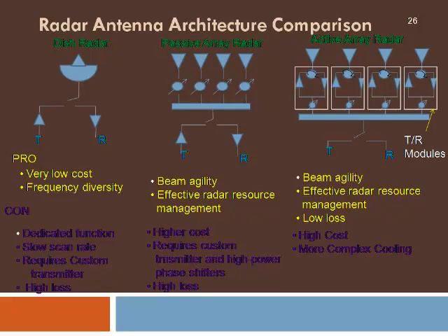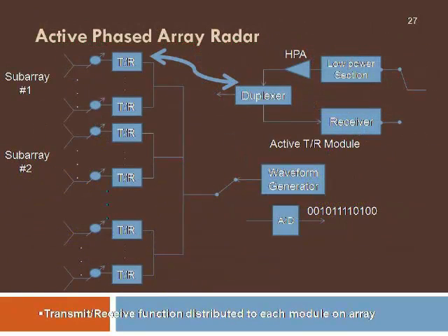properly with this. Here, when we go for an active phased array, we can see in this slide that there are going to be several transmit receive modules, and after this there are going to be phase shifters which will be programmed to see that the beam is pointing to different locations. There can be a single beam or multiple beams by properly choosing the phase shifter values. The TR modules will have separate transmit receive sections.